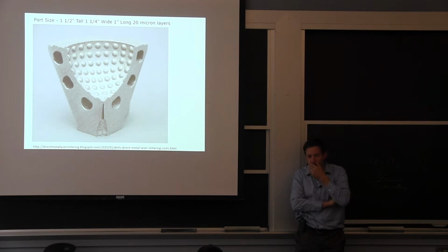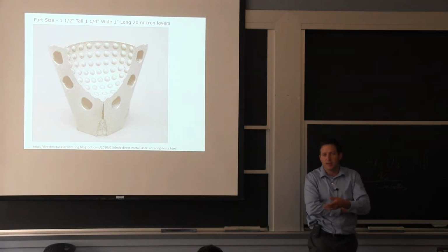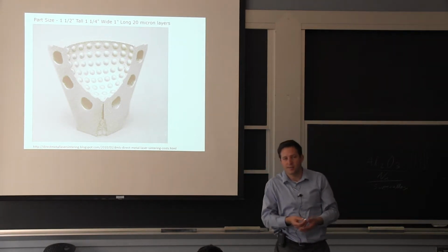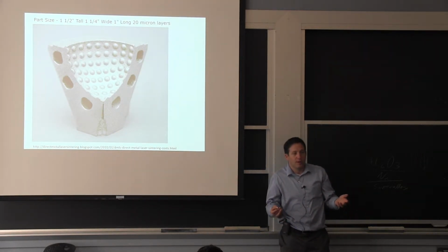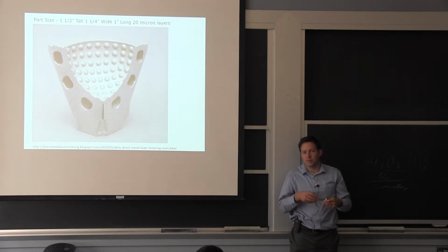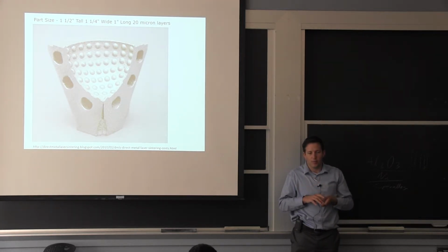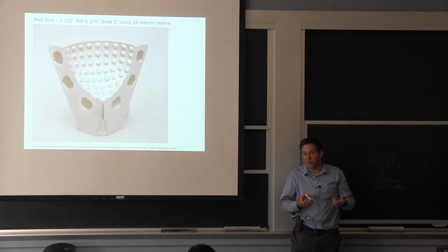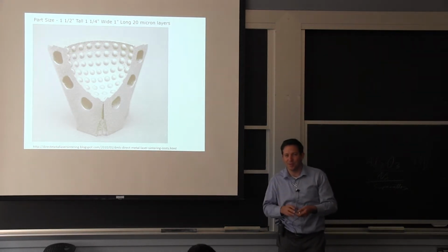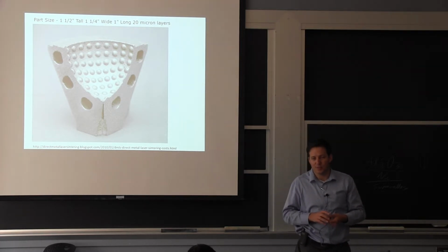And who knows exactly what else we're going to come up with. But right now you can make semi-prototypes about 1 inch tall, 1/2 inch by 1/2 inch, and they want to charge $400. So you can think like it's very, very expensive. At the same time, I can make something very intricate that will cost several times more through machining. So you save in any form of process development to the extent that you meet the printing requirements. And it's not really scalable, because if I need 100, maybe I get a deal, but it's not going to be 1/3 of the price, of course.